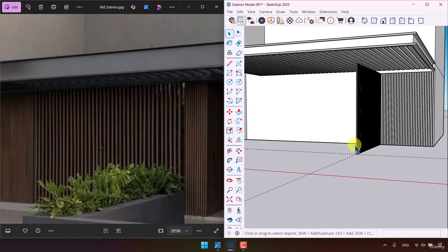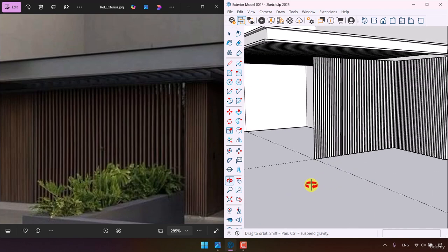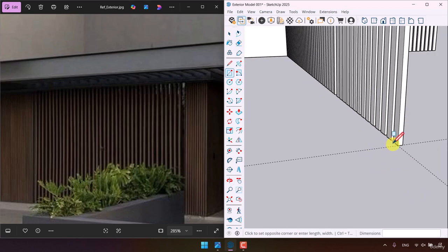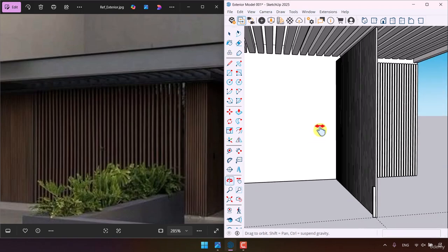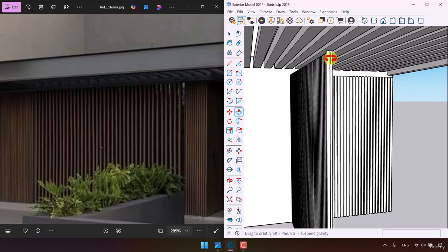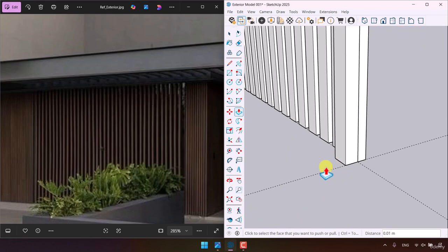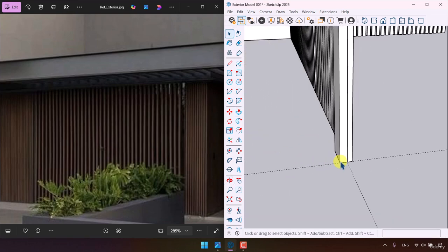So in this case, I want to generate a new type of copying system. So I can click on Rectangle, draw my rectangle like that. 0.03, 0.03. Click on the Push/Pull option, push it to the upside, some number like this. And now I can model it very simple. But these panels are a little bit wider than previous panels.